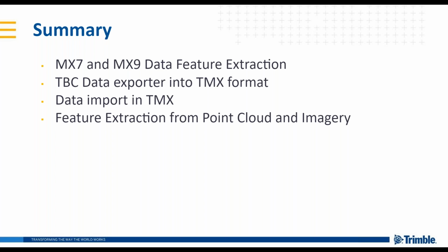We're talking about images. For point clouds, you have multiple options to reduce the point cloud processing time or the point cloud amount, as you have seen before in the previous webinar on the filter settings. We have a note here that TBC 520 will be coming very soon, and in that we can expect to export the point clouds with both RGB values and timestamps, which is currently not possible with 511.